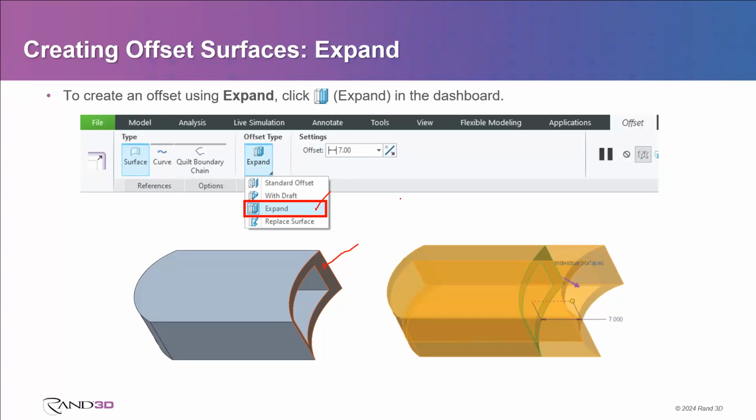So once again, we're offsetting to the inside of a radius. So there's going to be a limit as to how far I can offset. The radius of that original surface was about 16 there. As soon as I offset at 8, I'm going to get a perfectly sharp edge here, or exactly half of a cylinder. And that's really going to be the limit as to how far I can offset. The radius is getting smaller. If the original surface, the green one, had a radius of 16, and I'm offsetting by 7, of course, the new surface there would have a radius of 9 because we're offsetting to the inside.